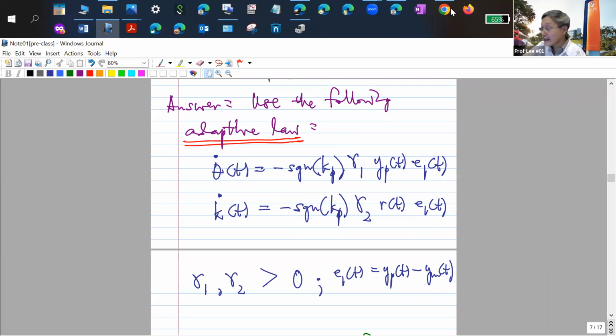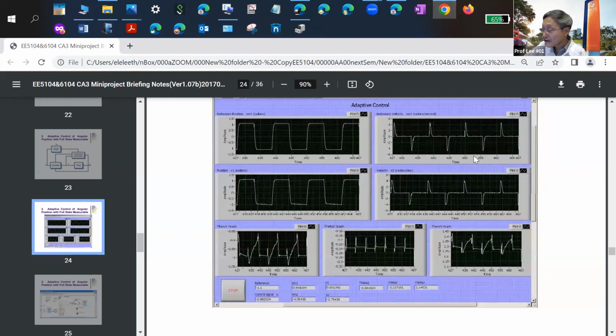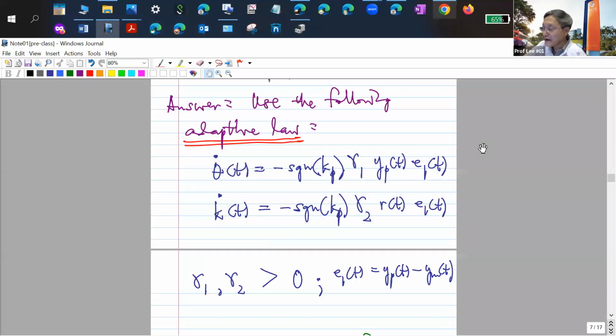It's actually like this. This is taking a simple step on the motor to see the sign of KP, and this is the moment they start the adaptation. This is real experiments, not simulated, and you can see the performance gets done almost straight away. Whereas if you use the Nussbaum gain, the first part of your performance will be very horrible. But never mind, this is just alluding to some of the ideas here.